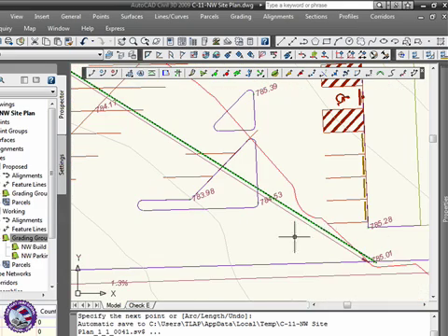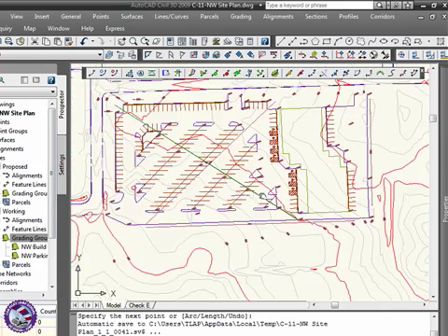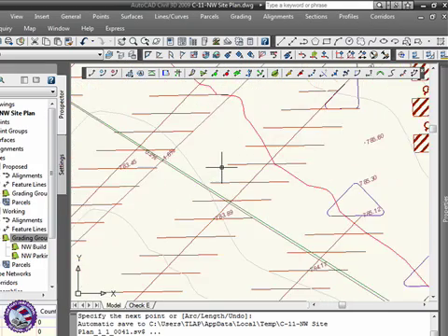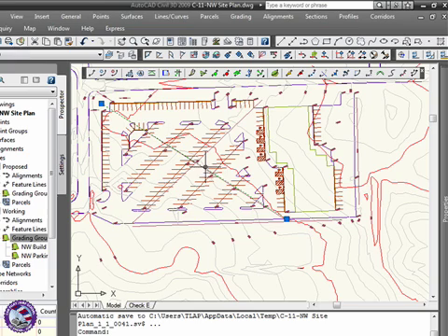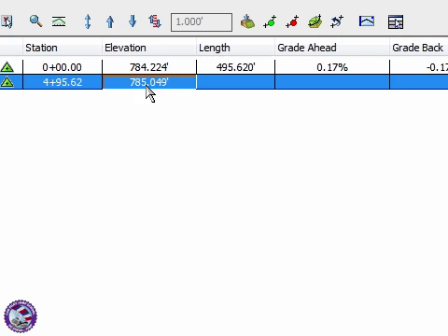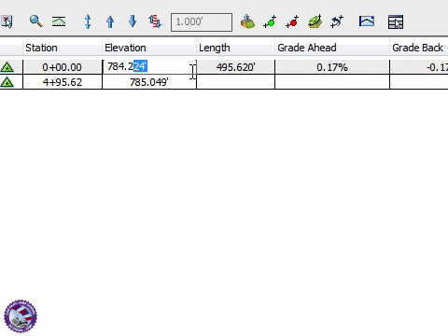You could carefully move them around, make sure that you are snapping to surface triangles, for example, and things like that if you want to move elevations. This is an editable object, and it has slope, so if I wanted to change the slope, change the elevation, I can actually edit those right there. For example, up here, I really like that to be at 225, and get rid of these hundredths, and we'll just make that a 0.5.